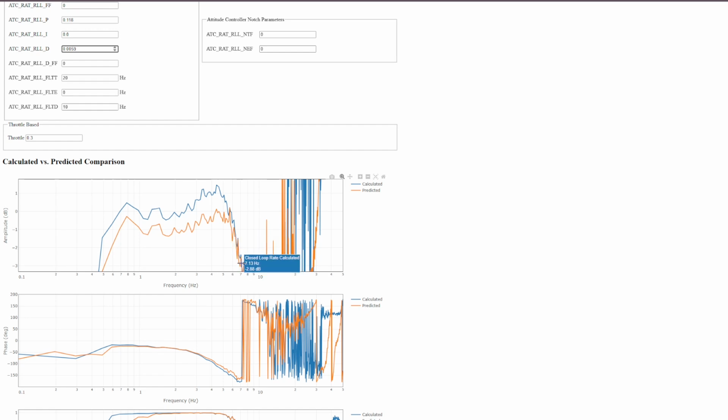So this is minus 3 dB here, so I want all of this orange to drop below that input there. There's a bit of noise, but we're getting down clearly below that. All right, so our angle P, we've taken this up close to 1 now. Now, in order to get maximum stability, if it was right on 0 dB, it would be critically damped.